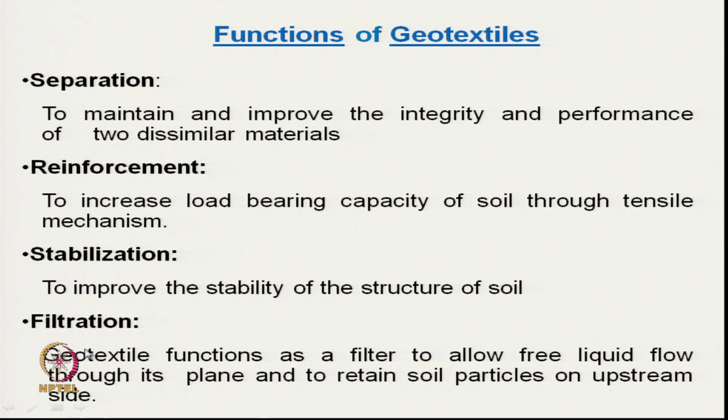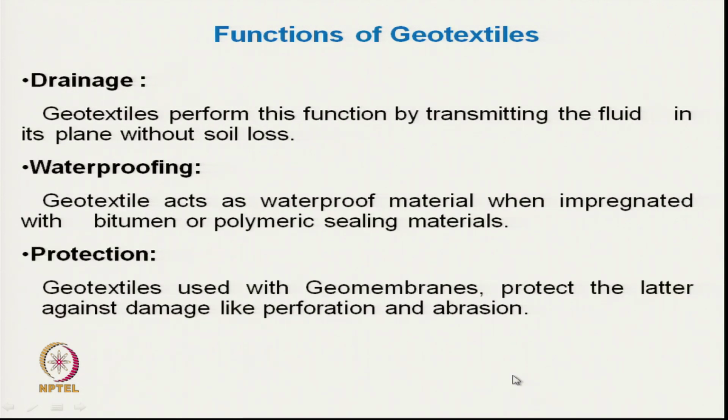Filtration, as we know, allows the free flow of liquid, in this case water, through its plane, but at the same time it should retain the soil particles. Drainage: geotextile performs this function by transmitting the fluid along its own plane.